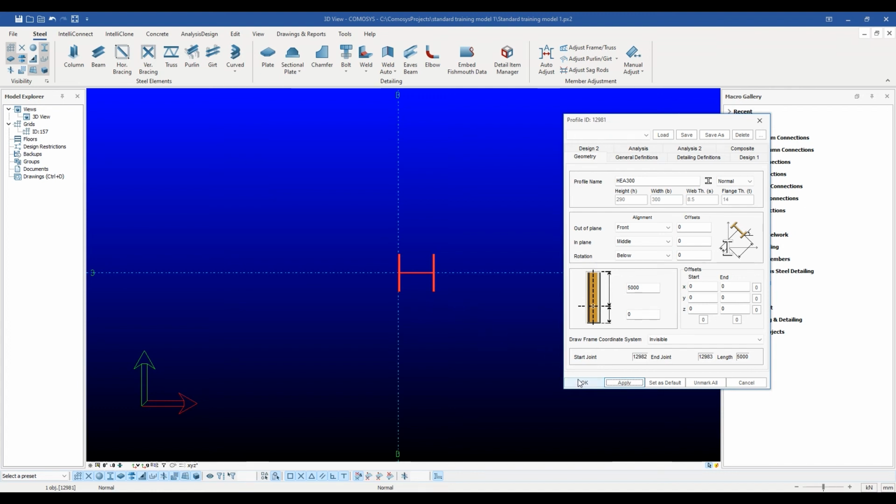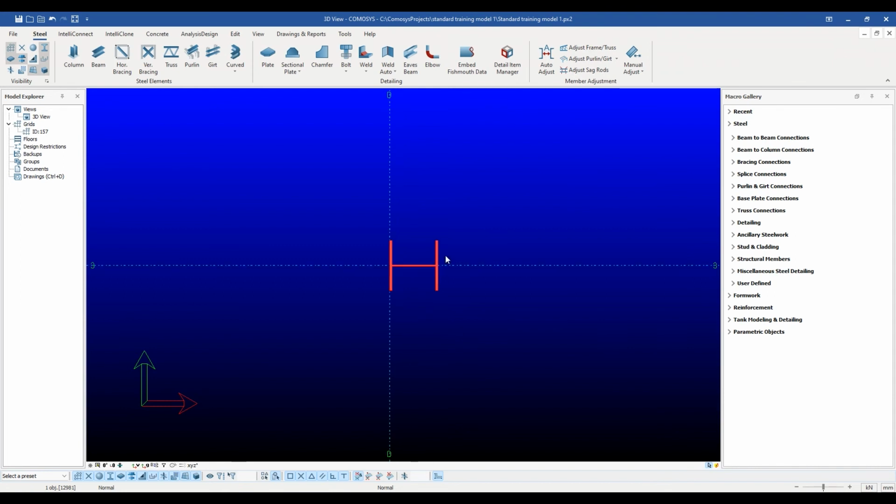It's important to note that these anchoring options are available as keyboard shortcuts. The rotation anchor, for instance, can be changed by selecting the profile and pressing Ctrl Q repeatedly until the desired rotation is achieved.